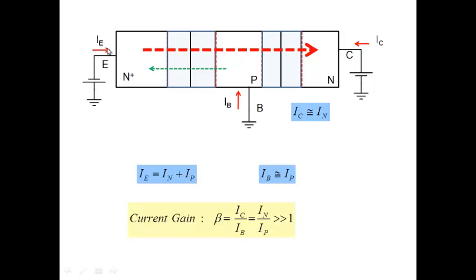The electron current here changes exponentially with the voltage here, which means that the collector current will change exponentially with voltage here. As I change my emitter voltage, the collector current would change exponentially. It's quite sensitive. So you can see here that IC is quite sensitive to the voltage that I apply here. The other point is, IC is not sensitive to this voltage.